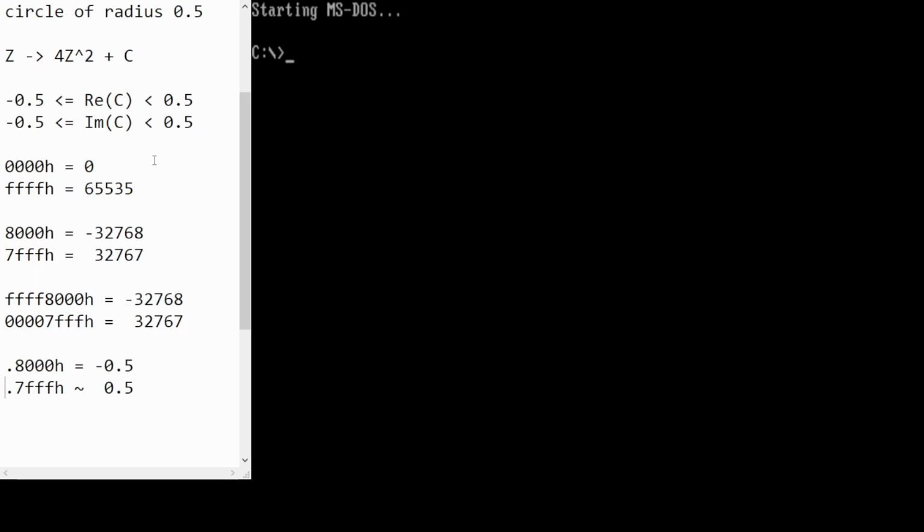You might recall that there are two different binary representations on the 8086 and 8088. There's the ordinary unsigned representation, which just uses the binary number system starting from 0 and going up through the positive values. And there's also the 2's complement representation, which allows us to represent positive, 0 and negative values. And the top bit tells us the sign, so if it's a 1, then we have a negative value. So in this particular case, we have a 1 in the top bit, and all the remaining 15 bits are 0 in binary. And this is actually the smallest value we can represent here. It's minus